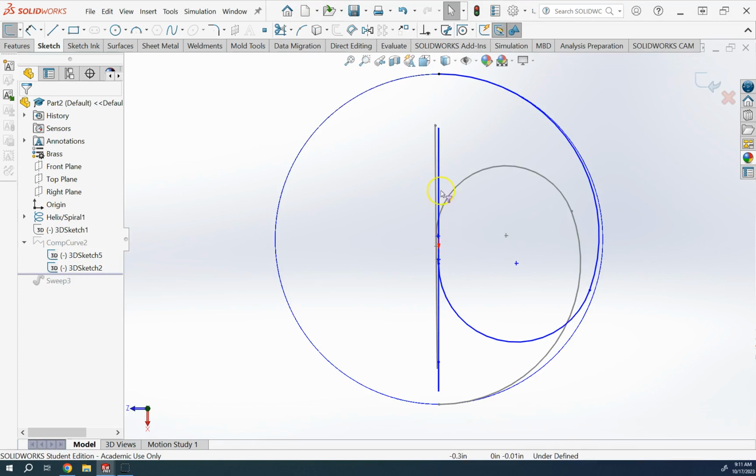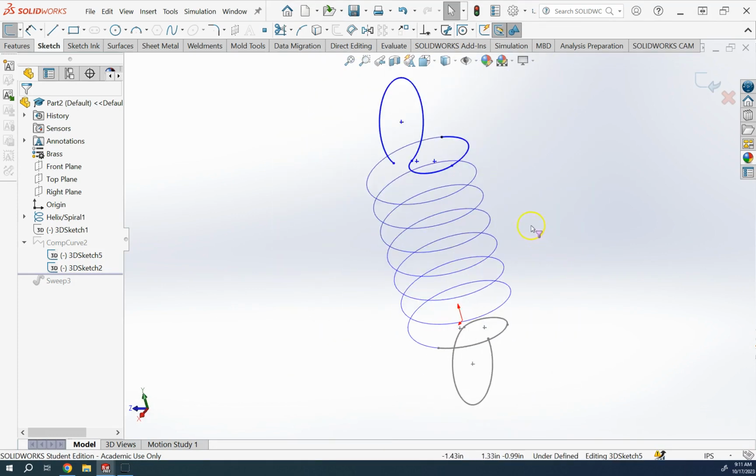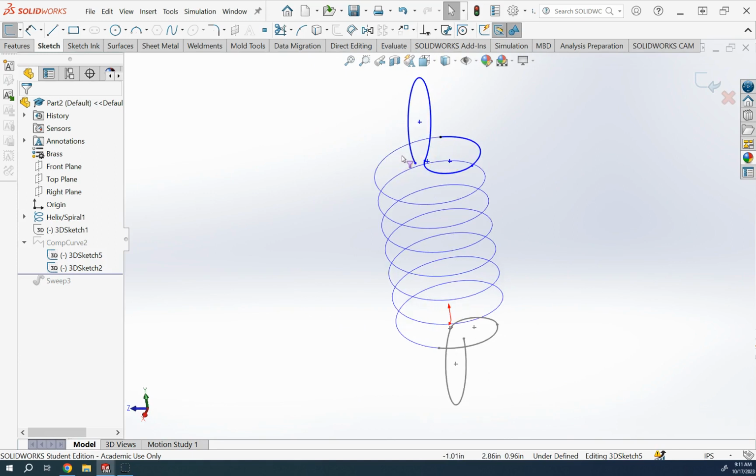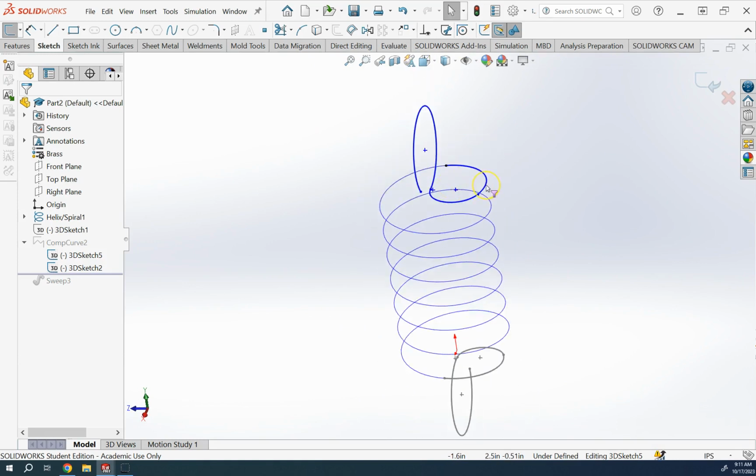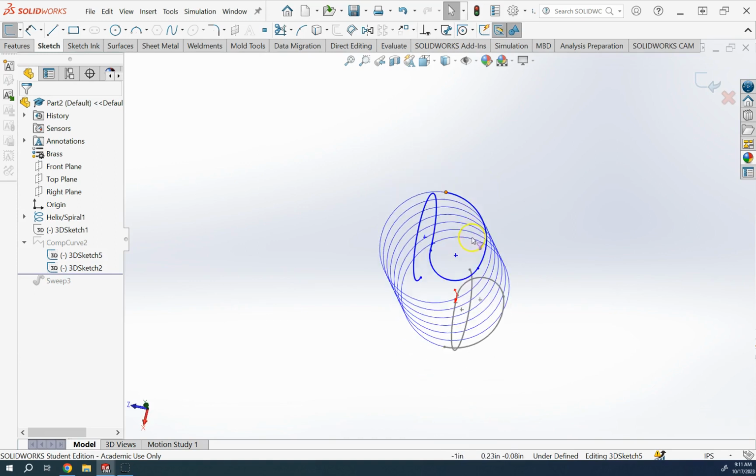So you see here, this is the top view. They end up around the middle, right? And here I did not provide exact dimensions, but you can provide exact dimensions. This is just something approximate, but I just want you to see how it is done. So again, a 3-point arc on XZ plane, another 3-point arc on XZ plane, which is smaller than the previous one, bringing it back almost to the center, and then a vertical 3-point arc on XY plane here.